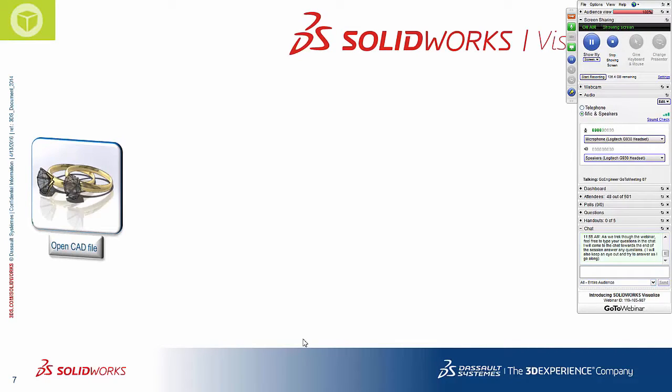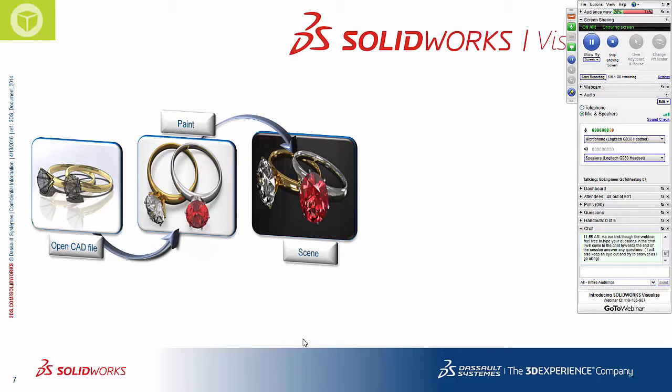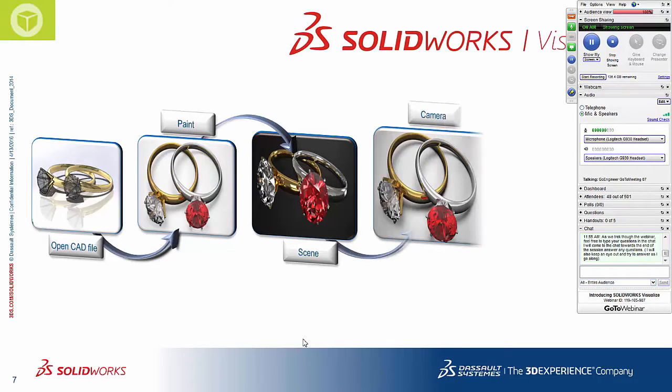All right, so we're gonna trek into Visualize itself, but before we do, I kind of want to set it up. So there are two different modes to SolidWorks Visualize. There's the simple user interface, and then there's the traditional user interface. Now, it essentially revolves around 5 steps to create a really nice, accurate render in SolidWorks. So the first step is open your CAD file, right? So you have an existing CAD file, you want to paint it, you want to make it look ultra realistic or more realistic than it looks in SolidWorks. So open up the CAD file, paint it, add the colors and textures and the detail that you're looking for. Apply a scene, so give it the proper lighting and backdrop that you're looking for, like a studio backdrop.